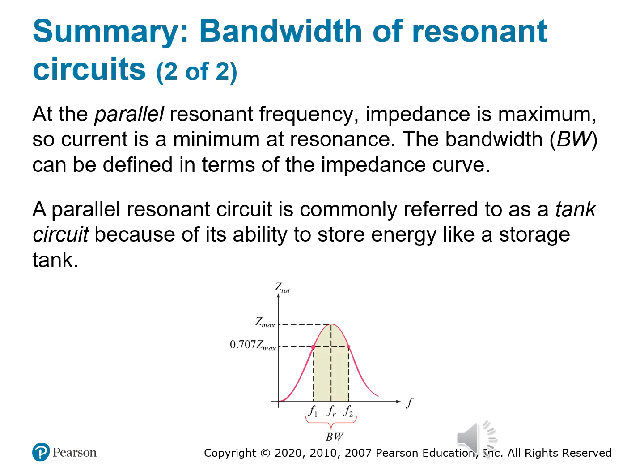And not because it's sluggish. Think energy storage. A tank circuit stores and transfers energy between the inductor and the capacitor, kind of like a slingshot being pulled back and forth. Right? Energy sloshes between the magnetic field of the inductor and the electric field of the capacitor.